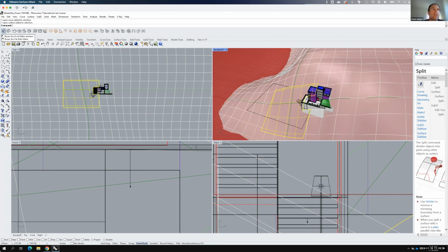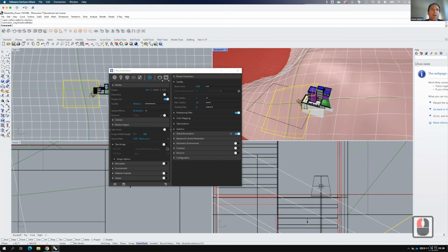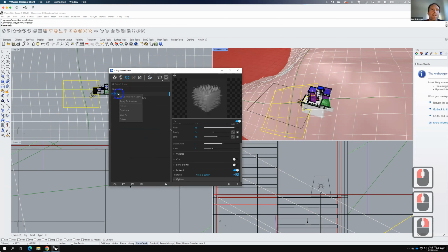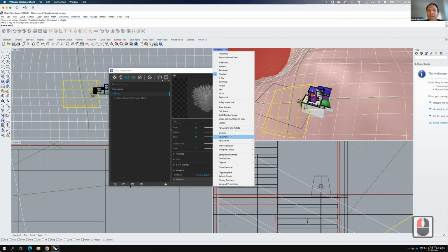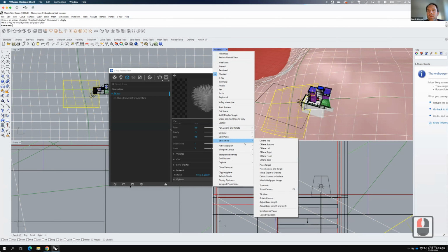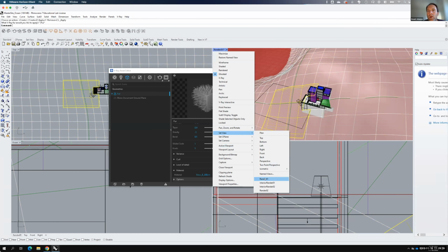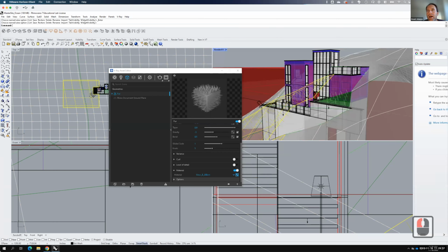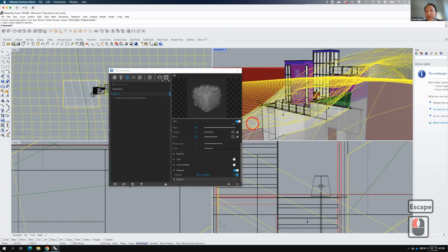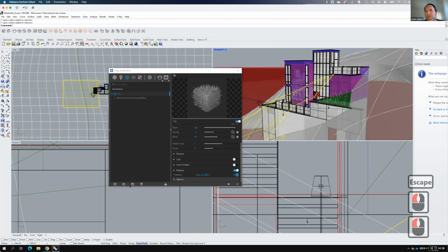So we'd go back into my V-Ray asset editor. We'd go back into my V-Ray objects, and we go ahead and apply to selection. We may need to make some adjustments, but it may turn out okay. Now we're going to go back into my set view, and we'll go back into my render one view, which was right here. It looks like I didn't quite cover it to the extent that I needed to. There's that little bit of surface. I might need to go a little bit higher toward that ridge.